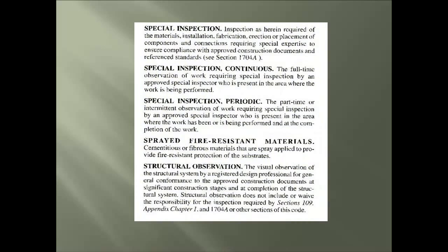It doesn't matter if you are the QC or the QA side. We hope this seminar will make you aware of the different roles that are involved with fabricating or installing material, and the first personnel is the special inspector. This person is a third-party quality assurance. Their duties are to observe the work being performed both in a shop or the field and report that compliance with the approved specifications and drawings and applicable codes are being met.